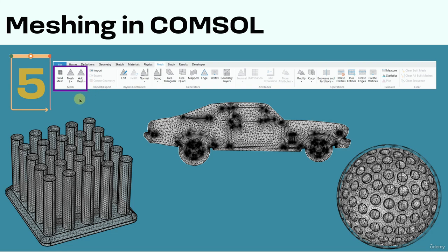So you need to be very careful while working with the mesh. COMSOL provides full control over generating the mesh. Under the Mesh ribbon, you will find this mesh section. In this mesh section, you can click on Add Mesh and add any sort of mesh.